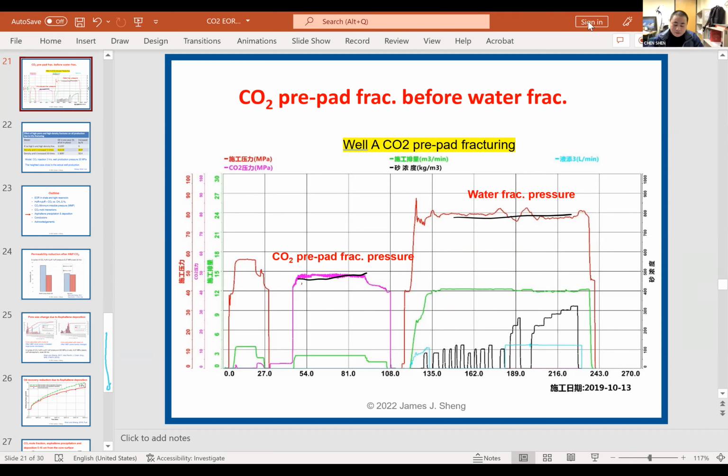Another question from our WeChat platform is, have we calibrated the miscible option used in the simulator with your lab test? What I present from my group is that all field simulation must be calibrated with experiments first, or calibrated with field data. Otherwise, you don't have a minimum verification, and then how could people trust your data?